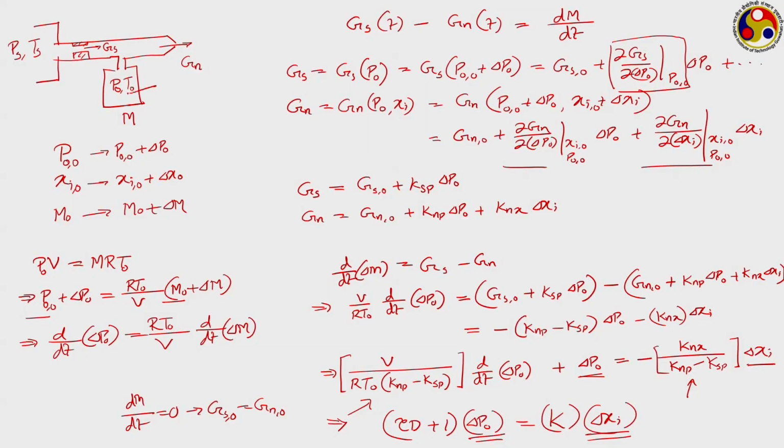Of course, the resolution of the instrument will depend upon the resolution of your pressure measuring tool, but if you have a sufficiently high resolution pressure measuring tool, you can have very high resolution of displacement measurement from this. So, though our objective is to measure the displacement on the flapper side, the tool that you will actually be using is something that gives the pressure at this particular tank, and once you have this pressure measuring tool working properly, you have an excellent option of displacement measurement.